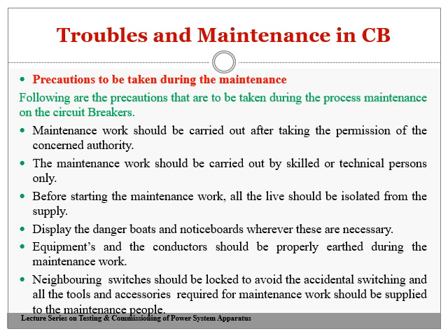Equipment and conductors should be properly earthed during the maintenance work. Neighboring switches should be locked to avoid accidental switching, and all tools and accessories required for the maintenance work should be supplied to the maintenance people.